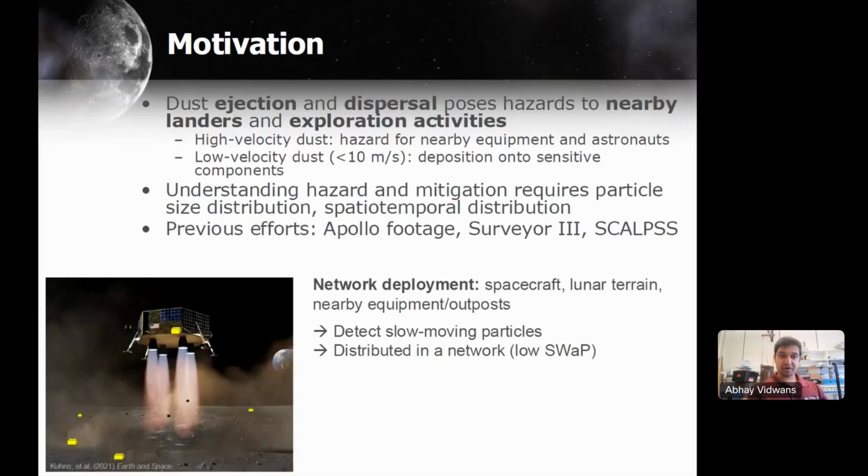As you all have heard in great detail, PSI events have a large effect on the lunar surface, including volatiles and dust, in a way that we don't fully understand yet. Now, as an instrumentalist, when thinking about measuring dust, I think about the velocity of the dust. For those familiar with dust measurements done in space, you know that impact ionization is a very popular method. This involves striking the dust particle against a surface where it turns into a plasma, and then you can use a charge-sensitive amplifier to measure the plasma coming off the dust, which you can then infer its size and charge.